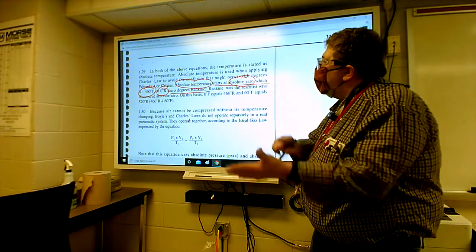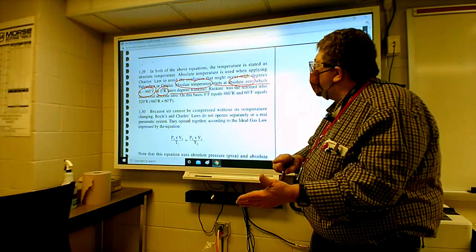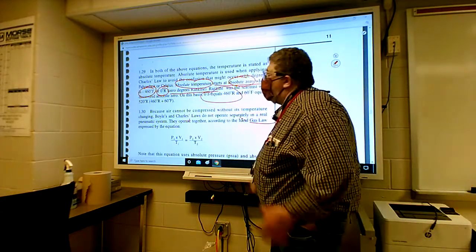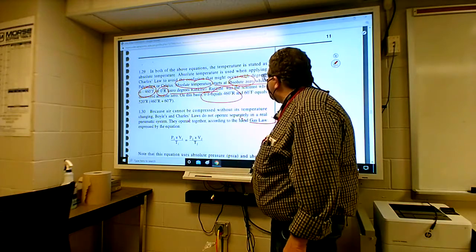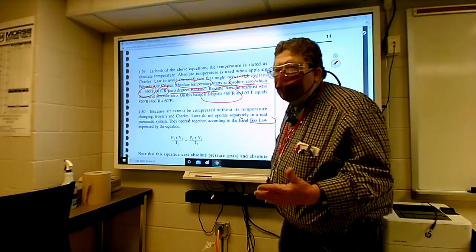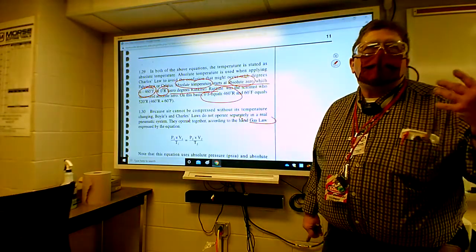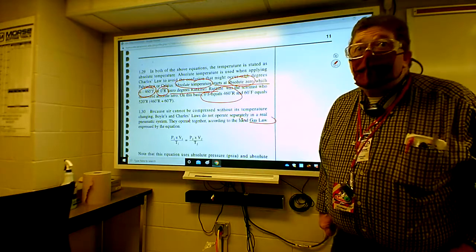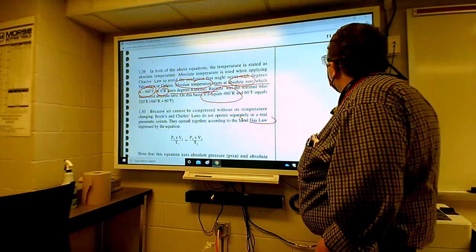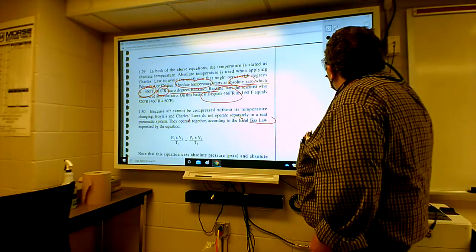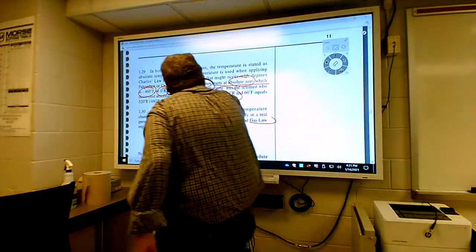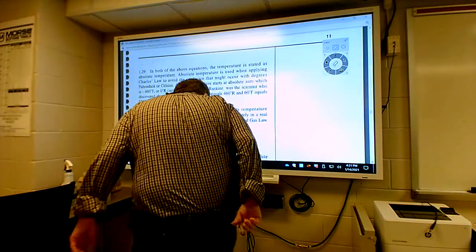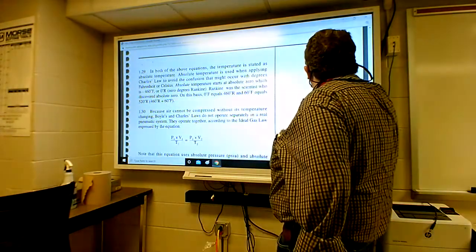But it's based on that absolute zero is minus 460 Fahrenheit, which is 0 Rankine, and then our 0 Fahrenheit would be a plus 460 Rankine. And then you got to add 460 to anything we have in the Fahrenheit system to give you the absolute temperature. Don't get worried about this, because we're not camping out on this stuff. We're going to do just what it takes to get you through the theory end of it. We're going to keep trucking.